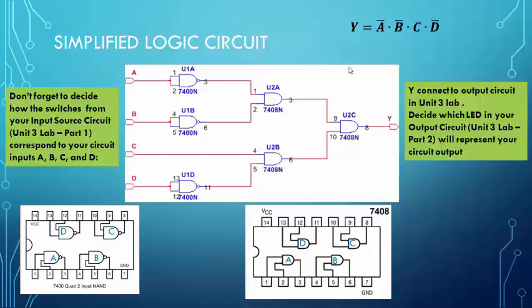For the NOT logic, we use NAND gates and short the two inputs together to represent a NOT gate. We talked about it in class already. If here's A, then after the inverter you should get an A'. So here's a B', here is C itself, and here is D'.